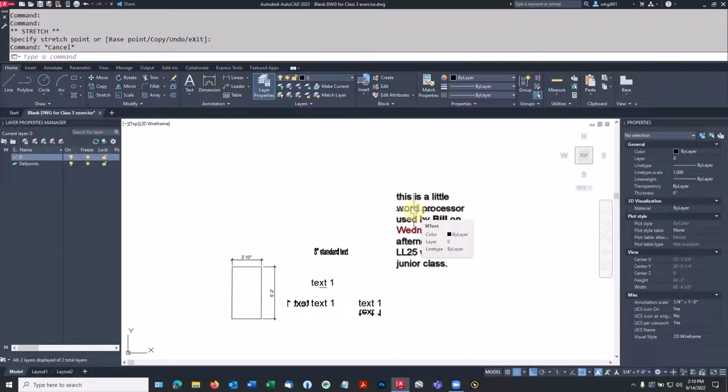I suggest that when you create text styles, you use names that describe the role of that kind of text in the drawing, not its font or height. If you decide to call it Times Roman 4 inches high, and you decide to use that for room names, well, let's just say you decide you really like your room names to be something else. I've got the style all set up, I'll just make them 10 inches high. But then the name of the style is wrong. You have to update a bunch of things at the same time, not only what's in the style, but the name of the style.